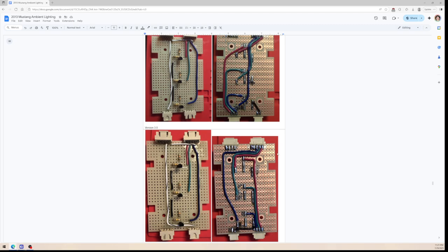These bumps here don't actually impact the way the circuit board works, so I wouldn't be concerned or worried about that. I just wanted to see if I could create one that worked in a way where there were no actual overlaps, which I did here. But again, I had to make sure that when I built my harness that would pull over my RGB signal, I would reverse the order of those wires, because the connector ultimately is in the same orientation. So that's ultimately the circuit in a nutshell.